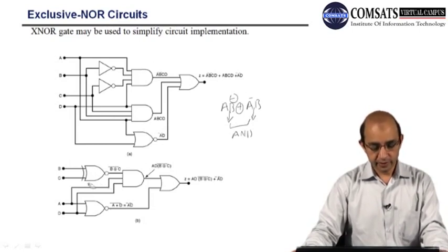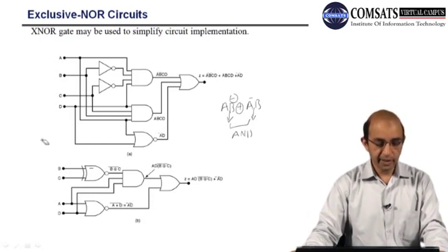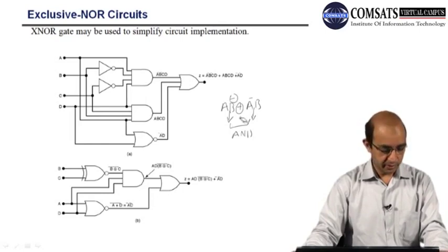Although this functionality, either XOR or exclusive NOR, is built from the basic Boolean logic: AND, OR, NOT. If you look at the expression, we have A B bar or A bar B. We have the OR operation, the AND operation, and the NOT or complement operation. So this is the XOR.